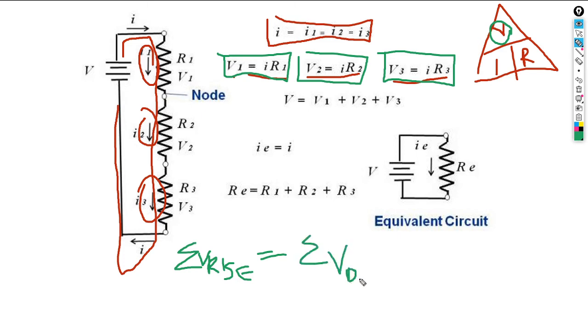What we mean by drop is the voltage across our specific component. So what happens is that our supply will be equal to the sum of the voltage drops in a circuit. So you can see that V is equal to V1 plus V2 plus V3. We're going to be using this formula more often because we really need to use this voltage rise, voltage drop circuit for Kirchhoff. So you should be used to this already, and I hope that you're going to be used to that.